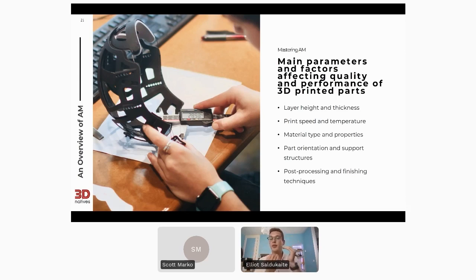If there is too big of an overhang, layers will tend to be subject to gravity, of course, and try to fall down, thus resulting in an inadequate result. So either you could be using support structures to make sure those layers are correctly supported, or in some cases, you can reorient your parts by as low as 15 degrees or sometimes 90 degrees, just to make sure you don't have too steep of an overhang and the print will result in success.